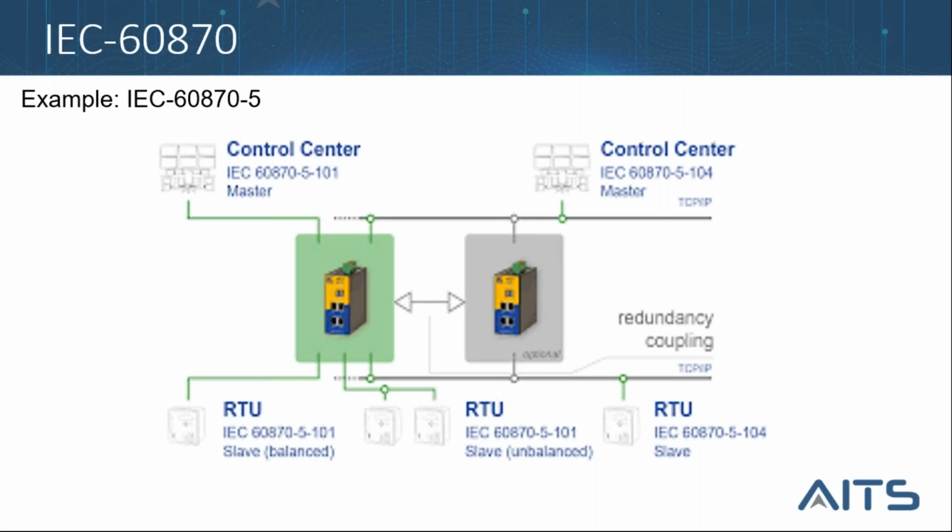The IEC protocol is the protocol created by the International Electrotechnical Commission, which is a standard that defines systems used for telecontrol. Such systems are used for controlling electric power transmission grids and other geographically widespread control systems. For example, the IEC 60870-5-104 enables communication between control station and substations via a standard TCP/IP network. The TCP protocol is used for connection-oriented secure data transmission.